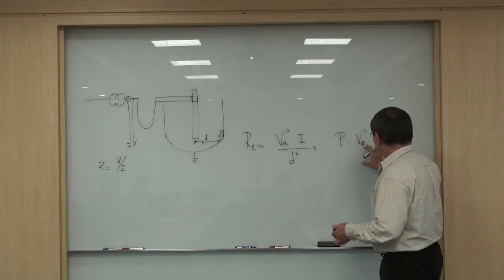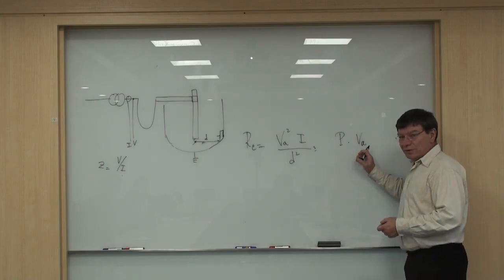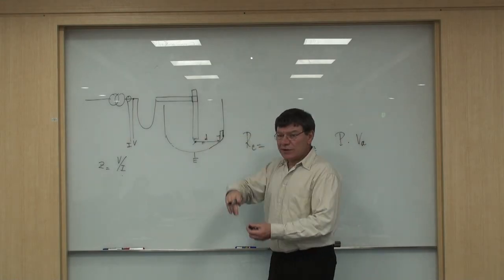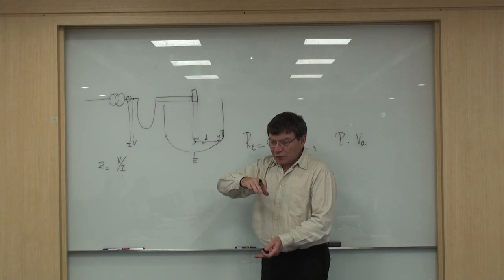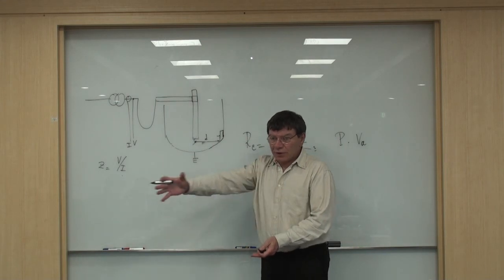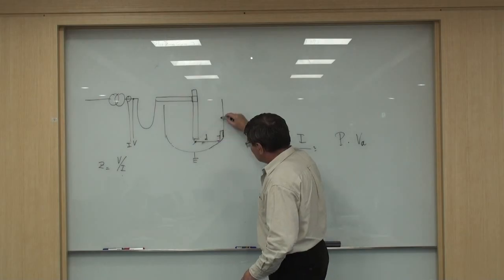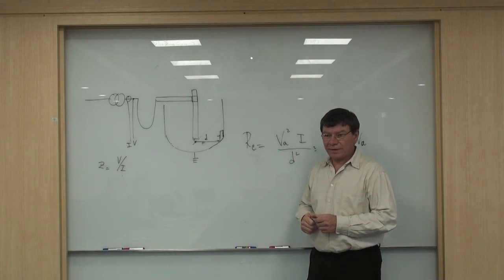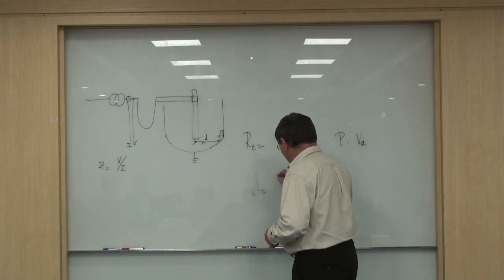But why do you also have more influence from the arc voltage? Because if you increase the arc voltage, you increase the arc length. And if you increase the arc length, you increase the solid angle where the arc is flaring.